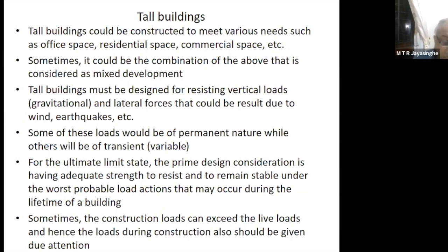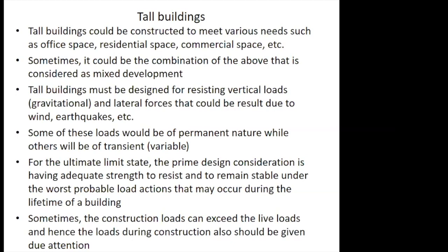So in Eurocodes, we get permanent loads and variable loads. And so basically, you have to ensure that there is adequate ultimate limit state strength, so that overall you will have a factor of safety of at least 2. And most of the concrete structures will have a factor of safety in the range of 2.5.